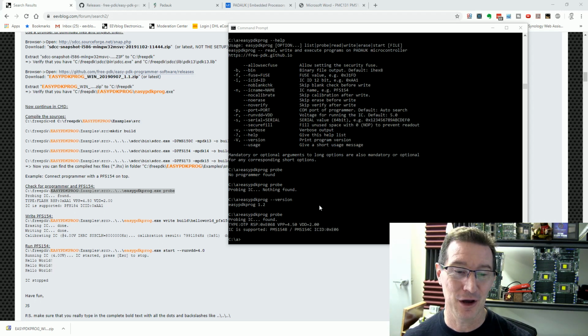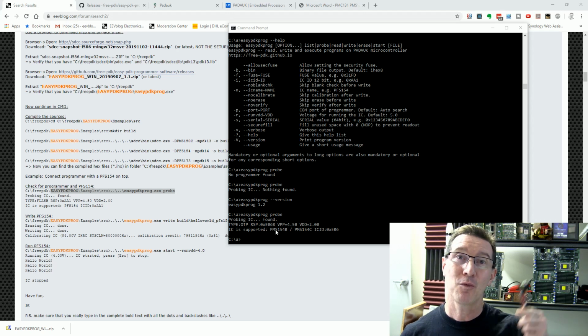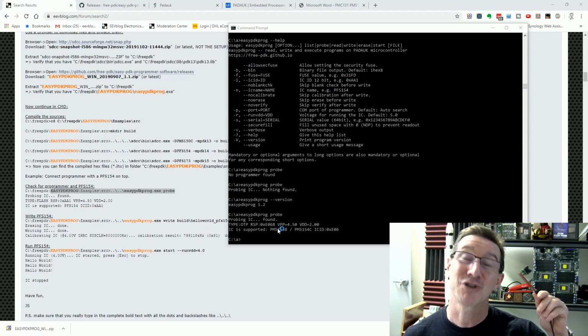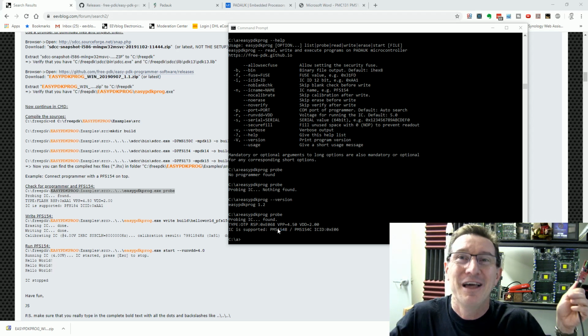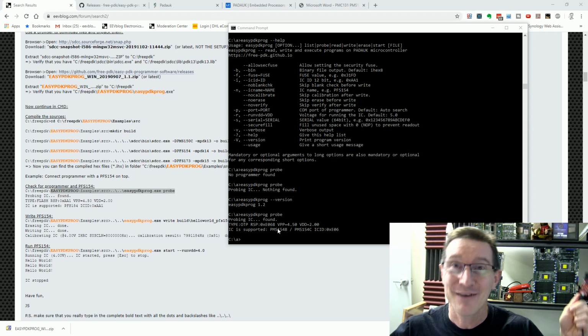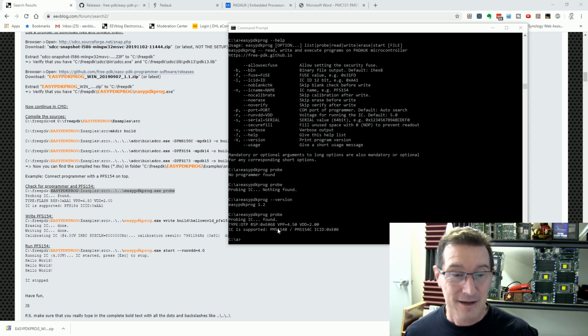Winner, winner, you know what? PMS154B/C, I guess they're identical. There you go, IC ID. What it was is that, yep, I missed a joint. I missed it on the inspection, and I soldered that joint properly. It was on the DC to DC converter. So that's one of the things that I didn't do in the previous hardware testing. And yeah, see? If you don't test it, Murphy will get you every time.